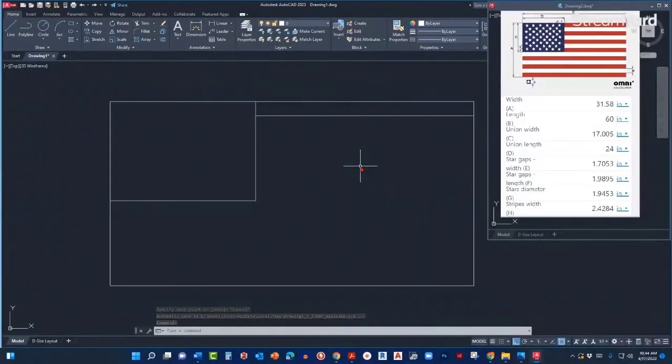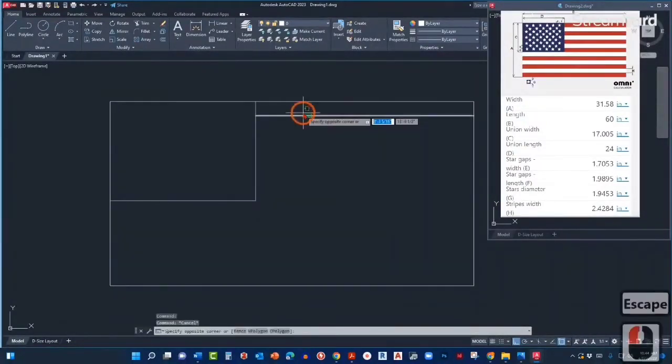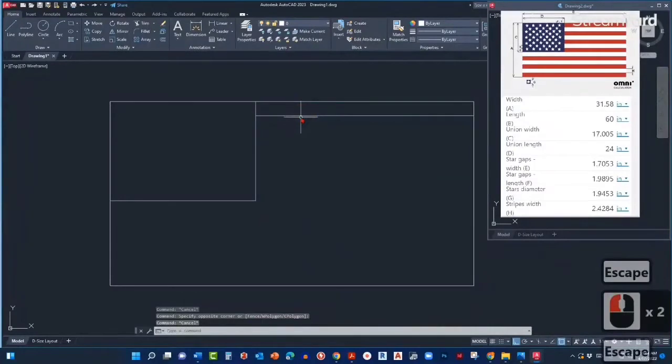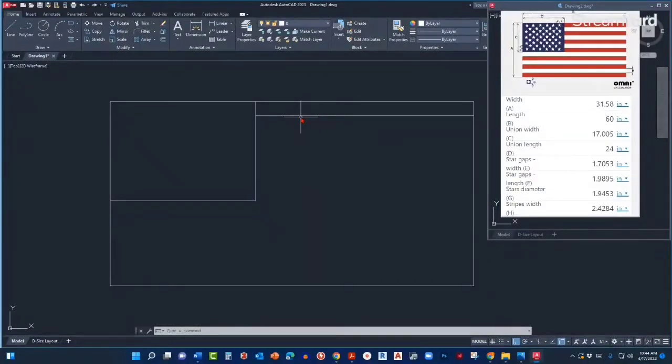And now to briefly explain to you the difference between line and the polyline. The polyline is simply many lines connected. So you have one line and two lines over here. They are connected. So that's the polyline. And this is a line, simply a single object. So by the end of this drawing, you're gonna know when to use the line, when to use the polyline. So let's keep moving.